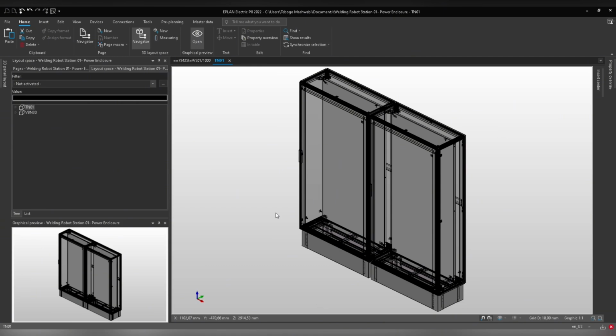So moving right along, the next question we had was with regards to the 3D layout space and the components which were inserted inside the 3D layout space using Insert Center, and also the components were not actually showing inside his reports. So the student was generating his reports, and what was happening is that the components and all the cabinet items like the enclosure items and the accessories were not showing inside his reports. So immediately I knew that he had a problem with his structures.